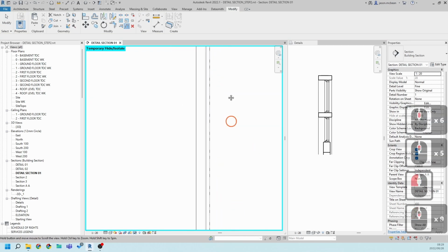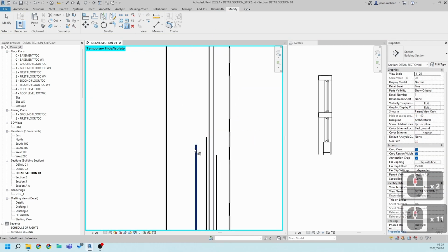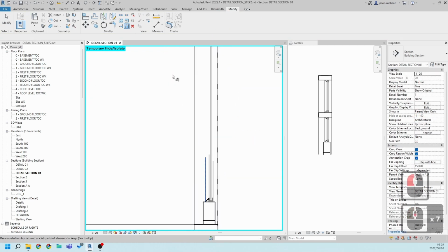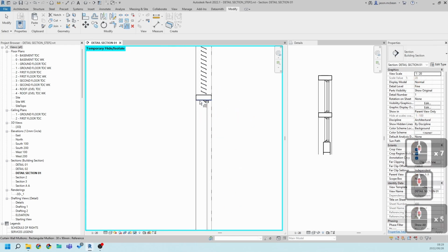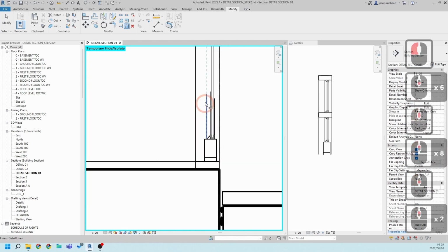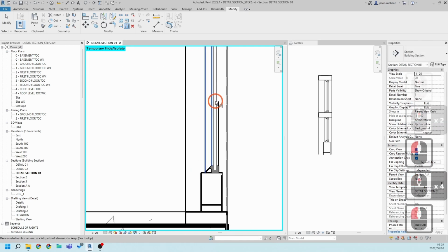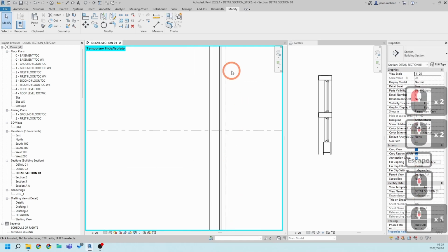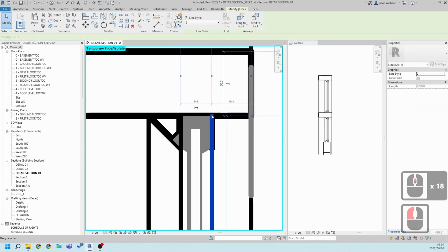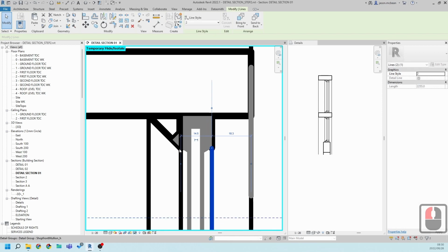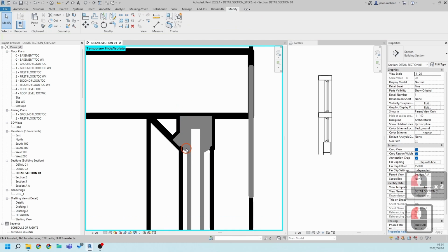Select this line for the time being, and then select all of these, and then trim multiple, my apologies. Select this object, good, and then that, and that. Once you go to the top, you can readjust these. Just remember there's a line weight behind, so you do have to readjust these to the correct location, just so that this information reads well.